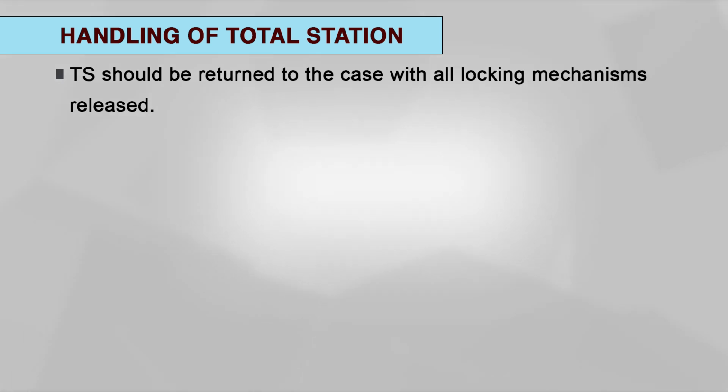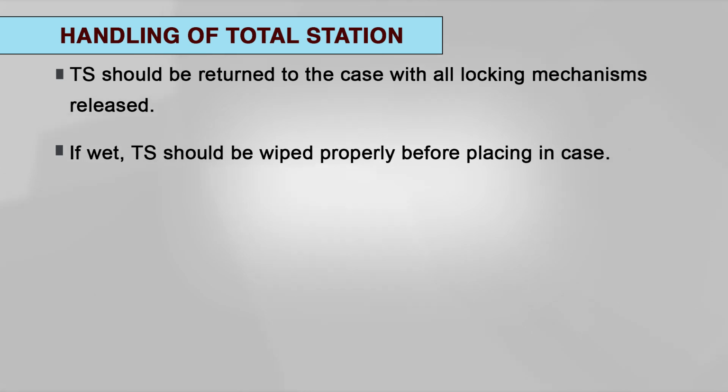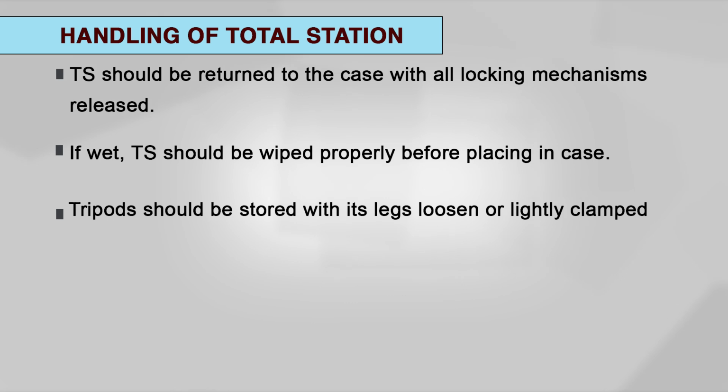The total station should be returned to the case with all locking mechanisms released. If wet, the total station should be wiped properly before placing it in the case. The tripod should be stored with its legs loose or lightly clamped.